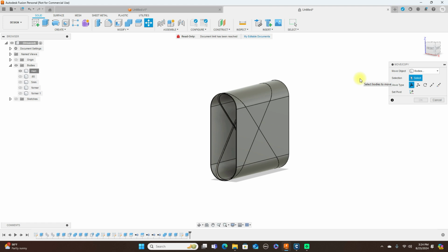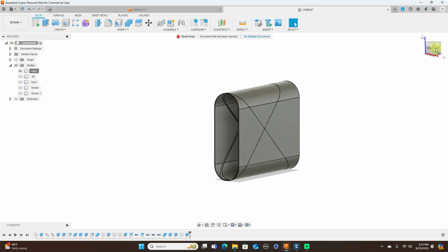Again, if you want to be able to print or design things like Plane Print does on some of the airplanes, like the formers inside, this is how you do that. And like I said before, with the wings, in my last video I showed you guys how to do the internal structure of the wing, so you can print that in vase mode. And that's pretty much how the Plane Print wings are. And you don't have to print those in vase mode if you don't want to. A lot of their planes do not have the holes cut out through the formers inside of there. So if you don't want the formers, just don't put the holes in there and cut those out. Just leave the formers all solid as they are, and go ahead and print like that.